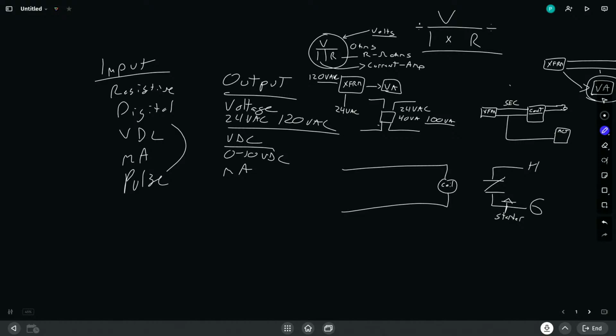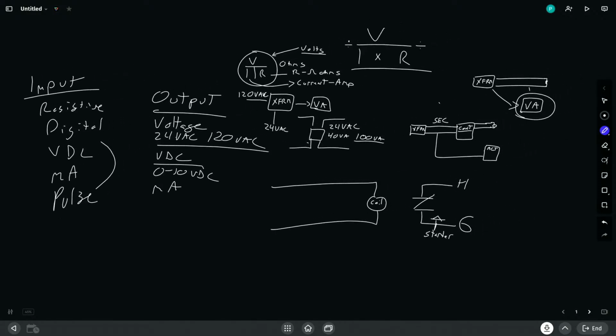That's because current, right? If we go back to Ohm's law, current is created by voltage divided by resistance, whereas voltage is created by current times resistance. So as we have that resistive effect, we are going to see more and more that we have some issues with our volts. And we're also going to have signal degradation from just noise in general over a longer distance.